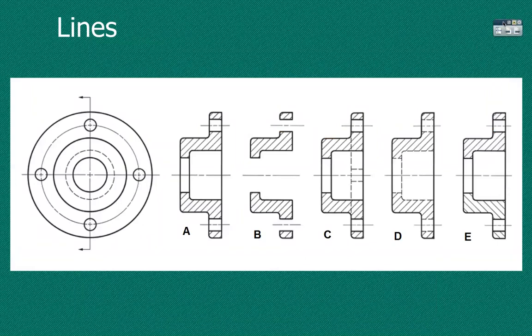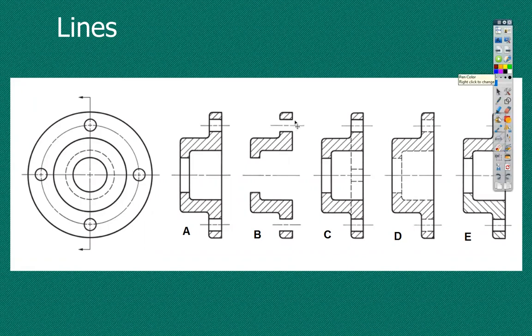When we do sections, we're going to see where we cut and everything beyond where we cut, usually. In most sections, you see where you're cutting and what's behind that. So which one of these is definitely wrong? B, yeah. That's no good because we're not seeing the back edges. We need to see that edge where it goes around the back side. This is showing us exactly what's cut and not what's beyond.